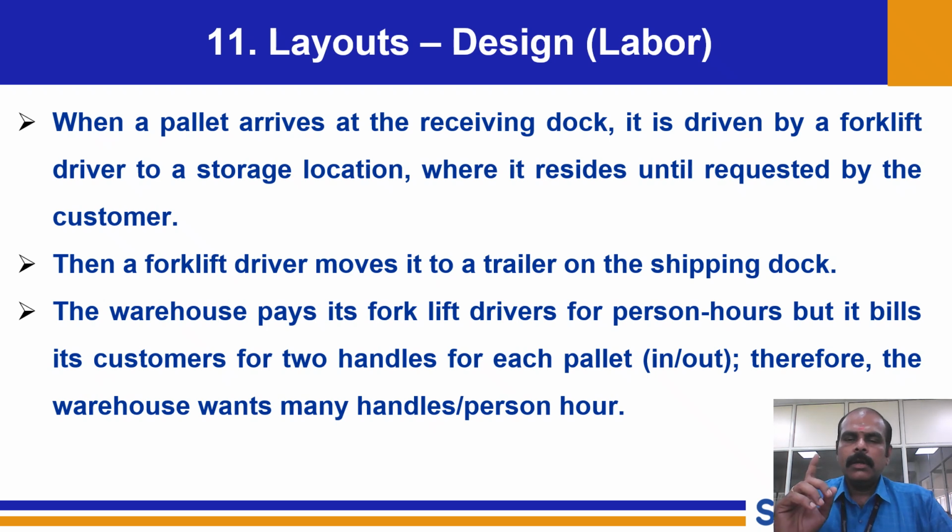Now, should this money be minimum or maximum? When we have this question, it is very obvious that it is supposed to be minimum. Whether they load or unload, the money we pay should be minimum. That means the time they take for loading and unloading should also be minimum. So that is going to be the objective: how to design layouts to minimize this. That is the second constraint. The first was the space constraint. The second is minimum material handling movement, whether by man or by machine.